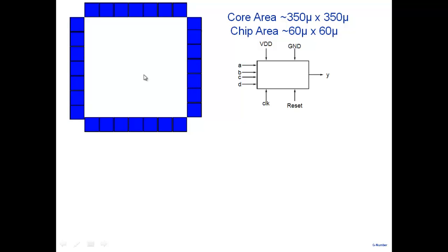It's a ridiculous design, right? No, I have a lot of space. I'm not using it. So what should I do? This one, so 26 is there. Normally what we try to do is make a die as square as possible in order to get as many dies from a wafer. So we don't want aspect ratios which are 3:1 and things like that.